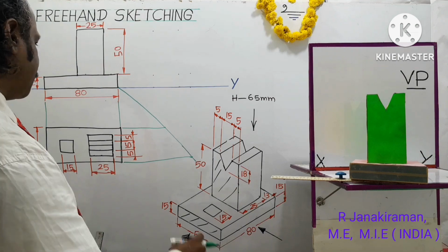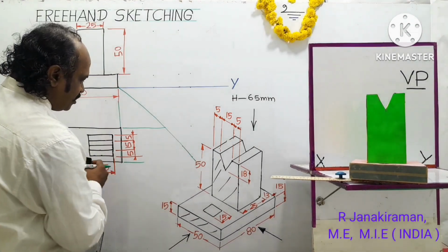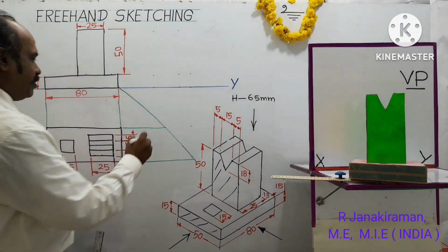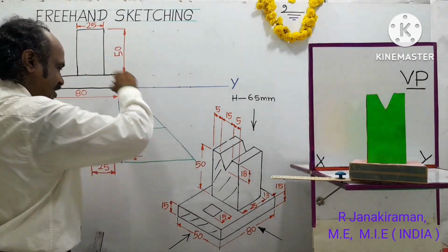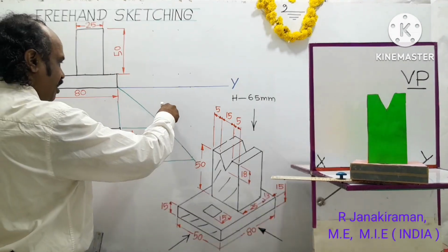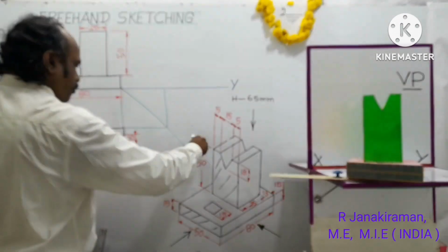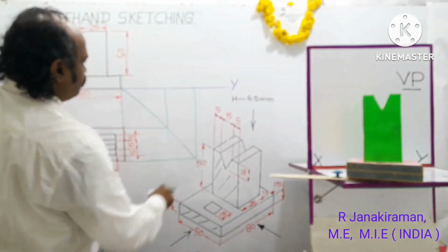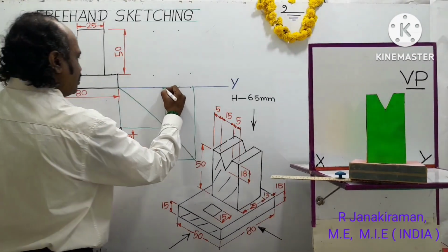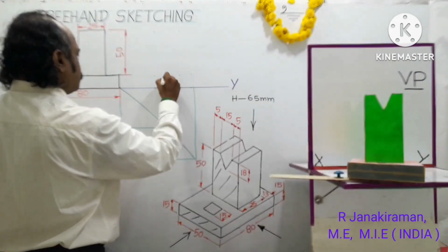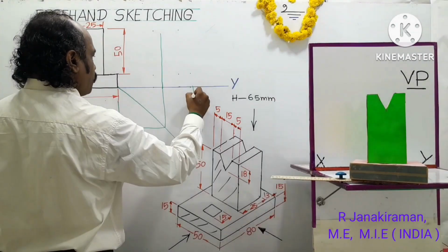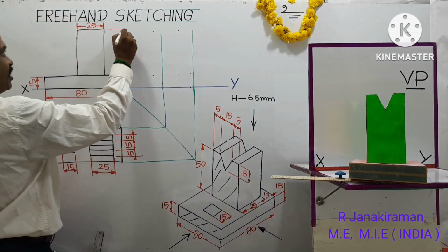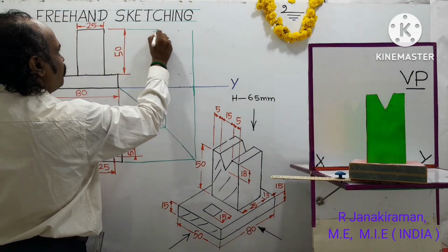The previous top view is projected by means of a projection line, drawn using a hard pencil. It's a lighter line. Where it intersects with the mitre line, there you draw a vertical projector. Understand? So extend this line further upward, and project the top surface of the previous front view by a horizontal projector.